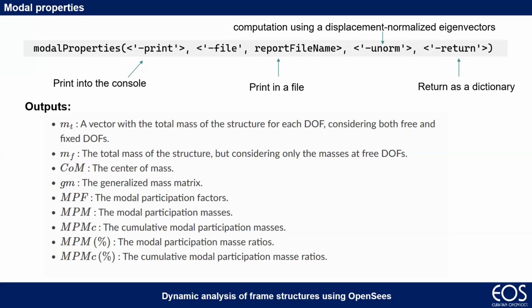So we run the gravitational analysis with one type of loads, and then as mass, another type of mass. So there are two different things: static analysis and eigenvalue, eigenvector analysis. So masses are for eigenvalues, loads are for static analysis. That's also the reason why you have to be consistent with the gravity acceleration. Otherwise, you will make a mess.